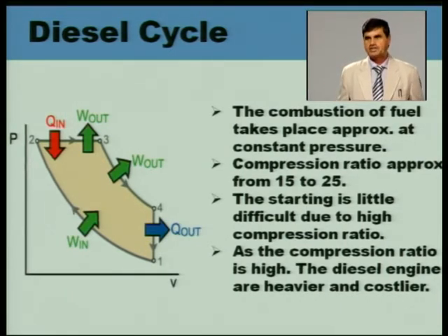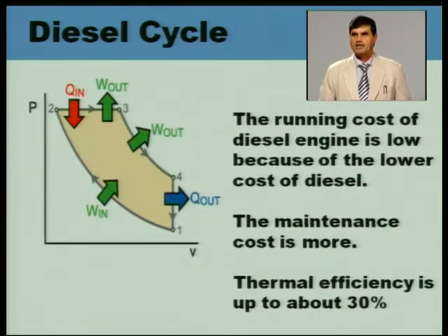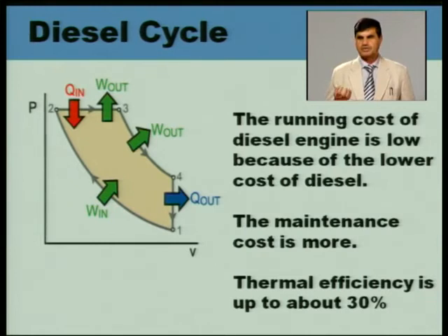So starting of these engines is difficult, and these diesel engines are heavier because they have to sustain high pressures inside the cylinder. The weight of the engine will be much more. If weight is more, the cost of the engine will be higher, but the running cost here will be lesser because the cost of diesel is less. Here maintenance cost will be more. They have to sustain high pressures, high temperatures.